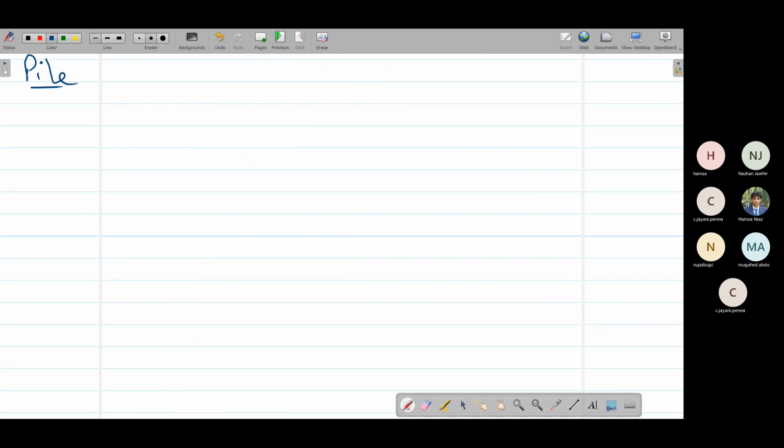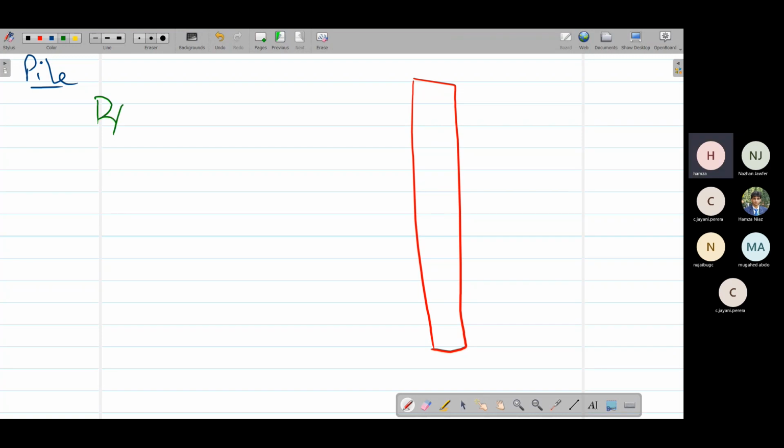So what is a pile? The pile is a long, slender member. It is composed of a number of materials like steel or concrete or wood, timber, etc. So it is a long, thin member whose depth of pile over width ratio, Df over B, is greater than or equal to 4. So this is a kind of deep foundation. Pile is a kind of deep foundation.